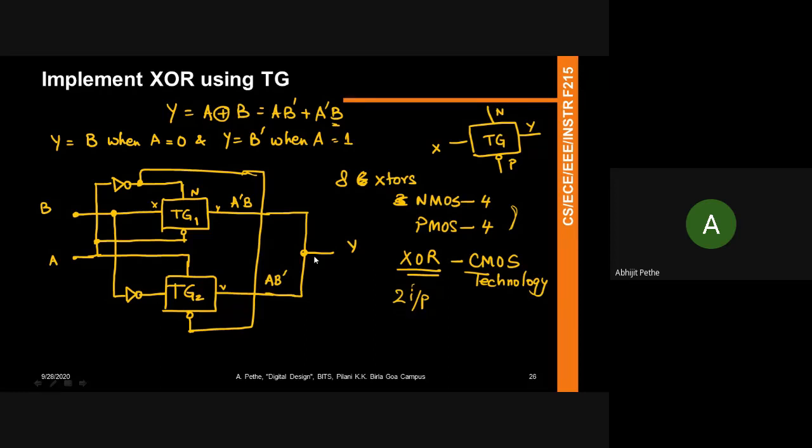Okay. So although TG decreases the number of transistors in the circuit, we still use CMOS because normally CMOS is used. We don't use resistors in TG, so CMOS is normally used, but sometimes for speed. One advantage of transmission gate circuits is they tend to be fast. So when you have a speed critical path in your design, you tend to go to a transmission gate kind of circuit. As you said, obviously CMOS is going to be low power, so you won't use TG all across. But for speed sensitive circuits, I will use TG. These are all choices that a designer has to make. You have to deliver a design, and you have to make the right choices.